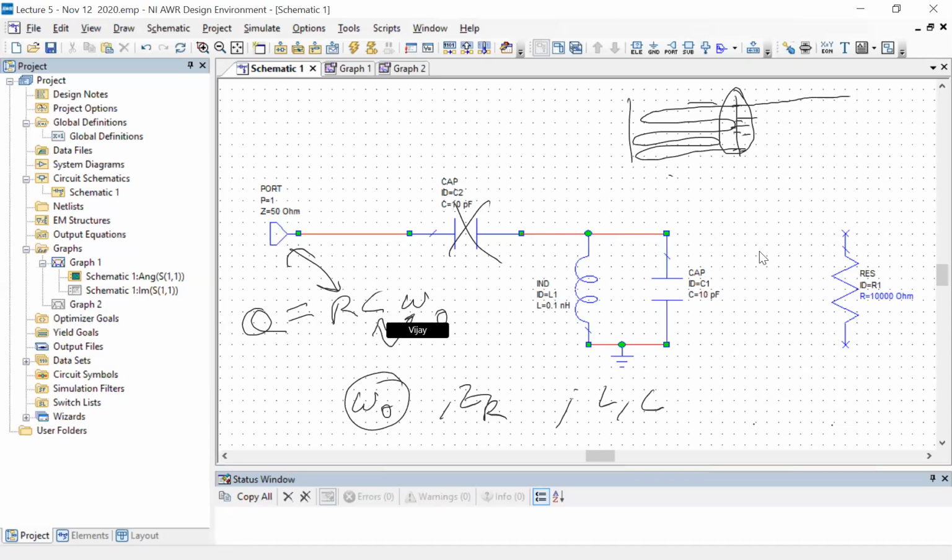Now, of course, these are not entirely independent, but when you rewrite, this turns out to be R over ZR. R is fixed. The only thing you can change is ZR. So what I was basically trying to say is that you can change ZR without changing omega naught. And that way you can tune the quality factor. Okay. Is that clear to everybody? I mean, this was something I mentioned fairly early now. Any other questions?